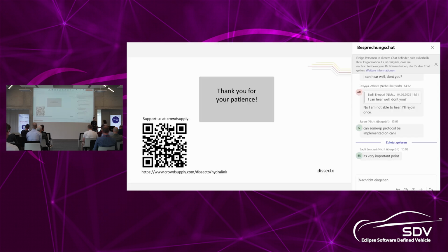Thank you very much. I'm checking if there's one question. Can SOME/IP be implemented on CAN? The whole idea of SOME/IP is that you can subscribe to PDUs which have IDs, and on CAN every message has an ID. So on CAN you don't need that mechanism to subscribe because you get the data anyway. Yes, it makes no sense. Okay, so that's been answered.